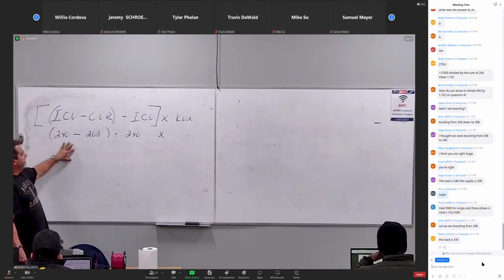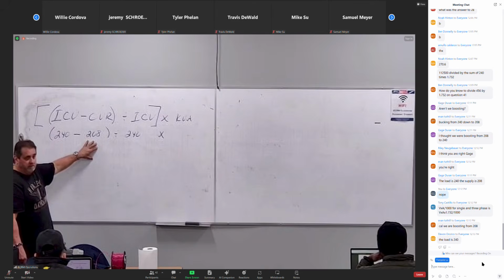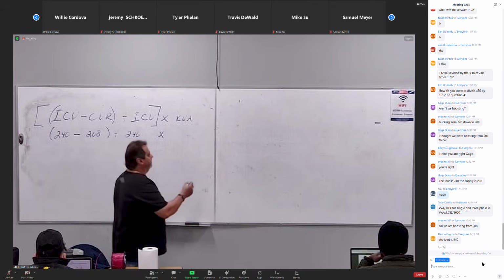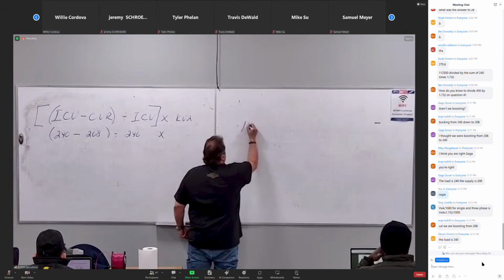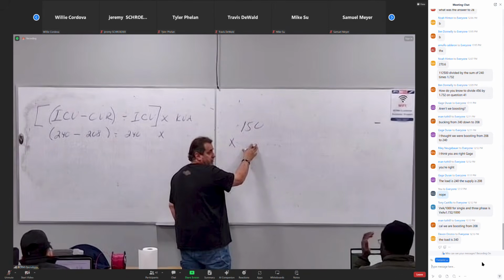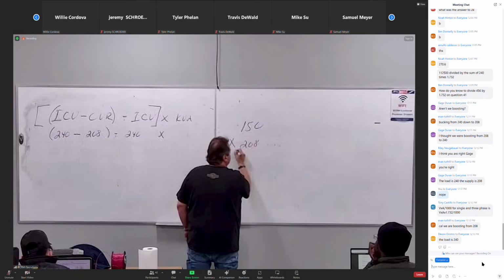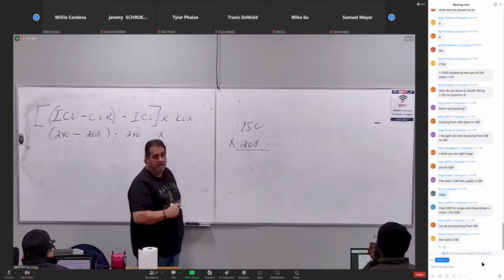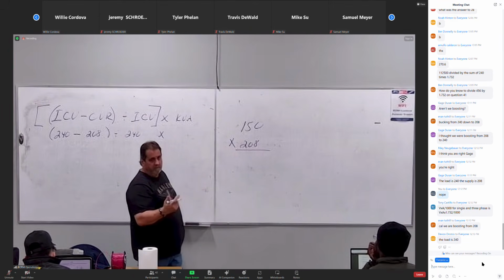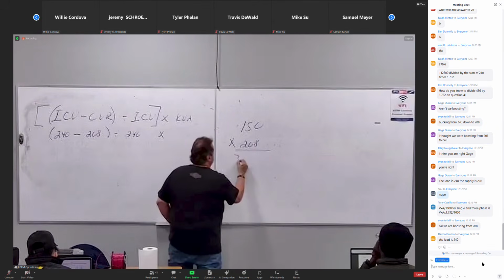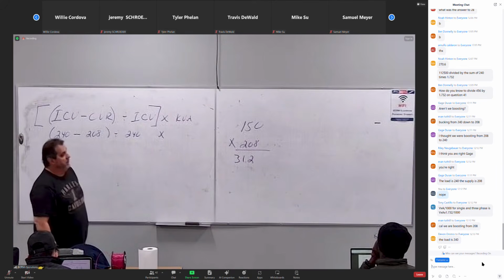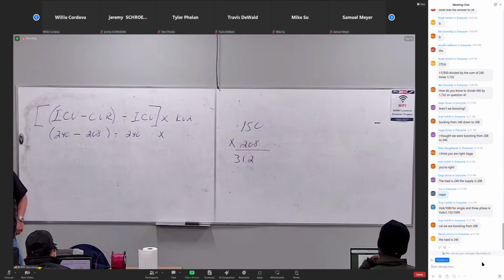So how would we solve this right here? We want 208 volts, right? And what's the amperage? 150. So to solve the KVA, we're going to take the 150 times the voltage that's required here, which is 208. That would give us our KVA. Does that make sense? That's what we would normally do. 31.2. Wait, where'd you get the 150? It says it in the question. It says it draws 150 amps.